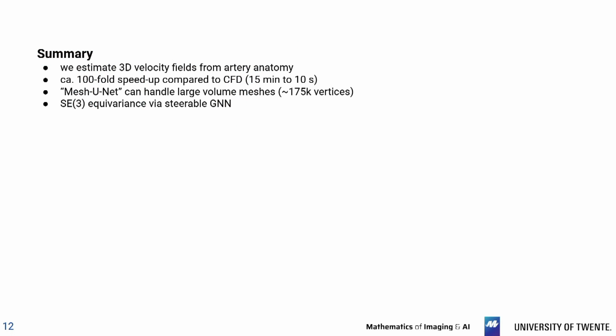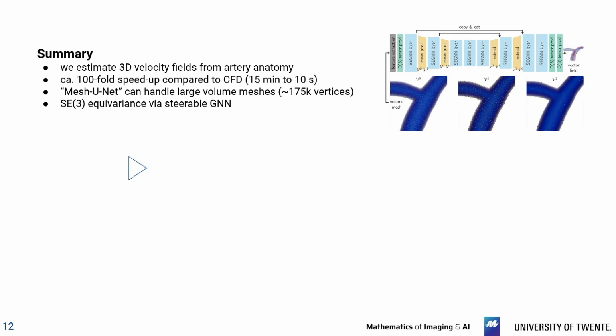Okay, in summary, we built a surrogate method that can be a task-specific surrogate for computational fluid dynamics if you have a lot of data. We handle the large meshes with some sort of pooling, and the method is equivariant to rotations and translations.